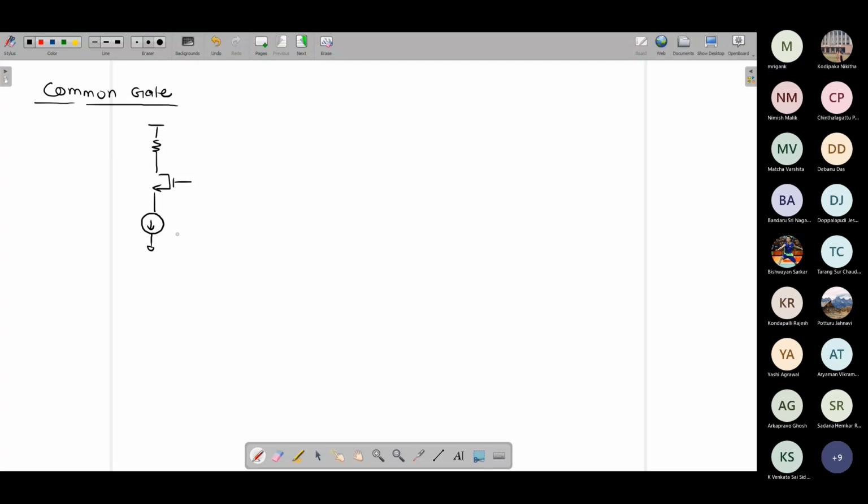For example, if we consider a voltage to voltage amplifier, in that case we can assume capacitive coupling. So this is a common gate amplifier where the input signal is being applied through capacitive coupling. Suppose this is the input stage, and you are going off chip. This is your sensor signal V incoming, and there is a coupling capacitor.